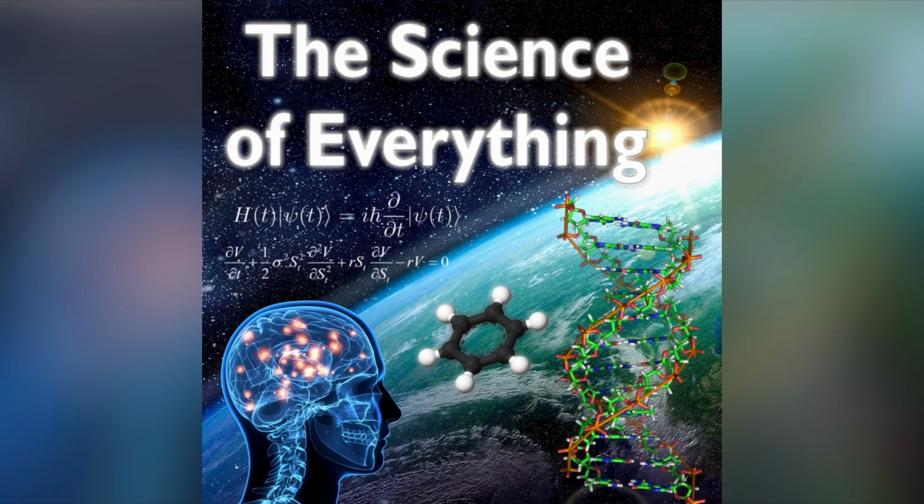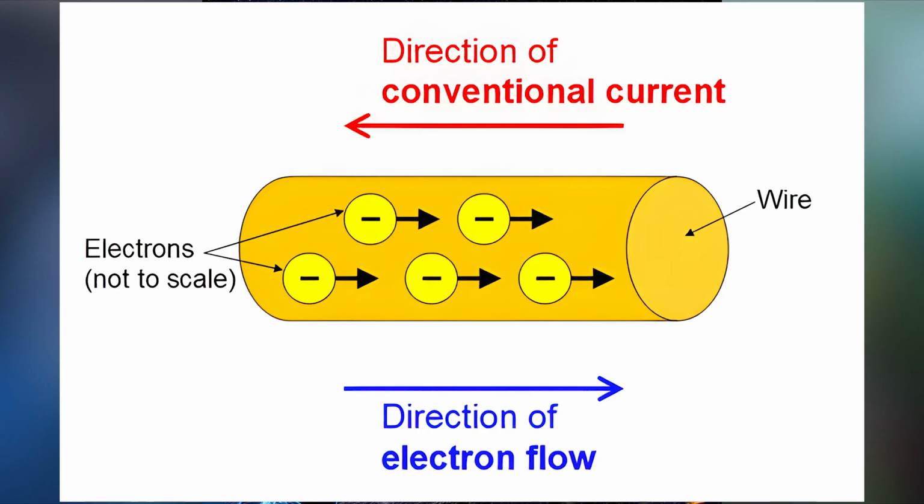Gases can also carry current, so it doesn't have to be a solid to carry current, although that's usually what we think of. By convention, and this is quite confusing, current flows in the direction that positive charges move. That might sound reasonable enough, but remember, most of our electronic devices run on electron motion. So if the electrons are moving from left to right in a wire, that means the current is actually going from right to left. It's going in the opposite direction to the electrons. That gets really confusing in electrical engineering and other fields, where you always have to remember that the current is flowing in the opposite direction to that in which the electrons are moving.